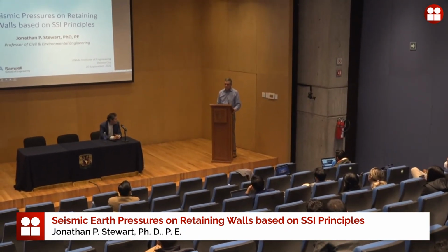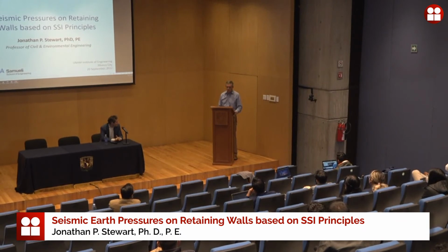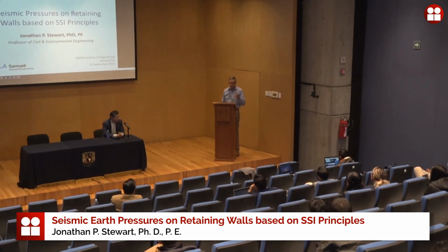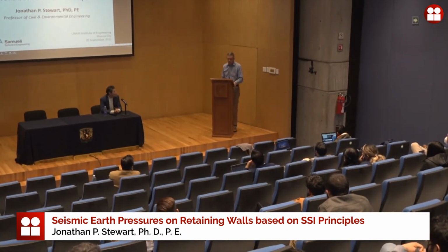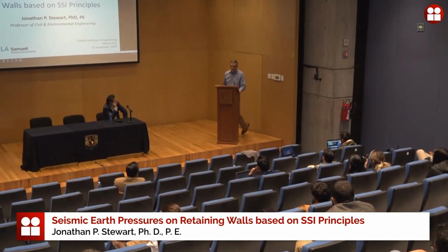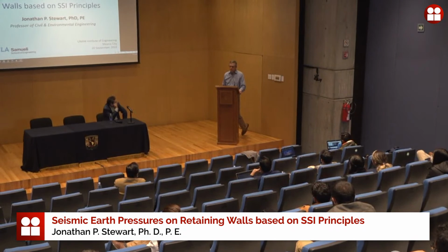Well, this doesn't deal with pore pressures that develop as a result of liquefaction or softening of clays, right? So these are total stress solutions. When you have strength loss due to pore pressure increase, it actually makes the static earth pressures, those that would be there even if there was no earthquake force, go up considerably. It also reduces the resistance at the foundation. This is why we see so many problems with that. So this is a total stress solution. It doesn't deal with that problem.